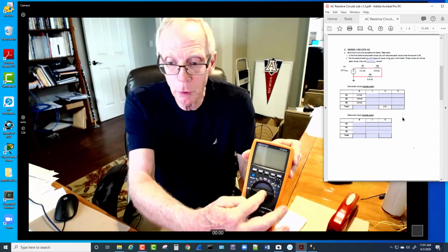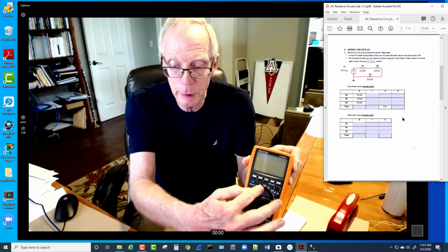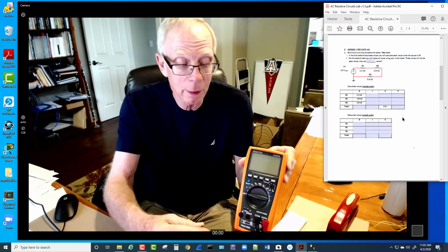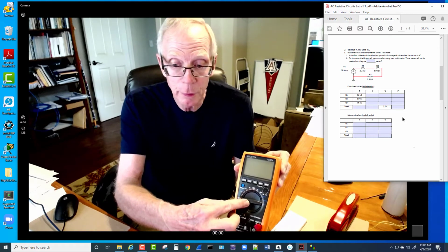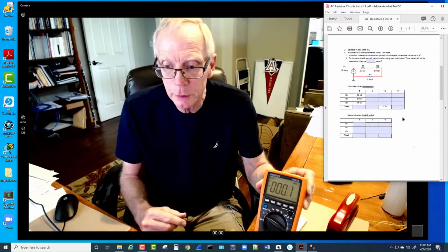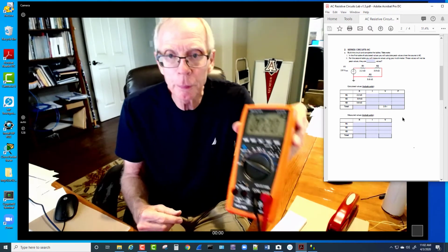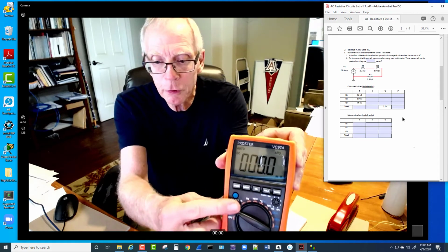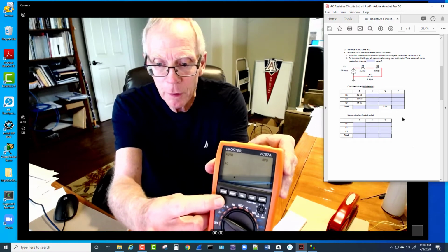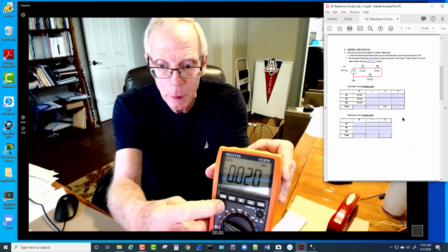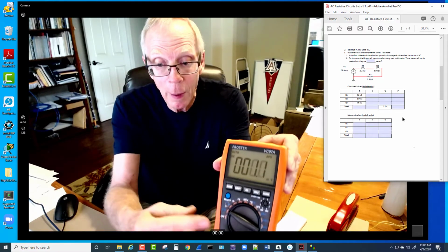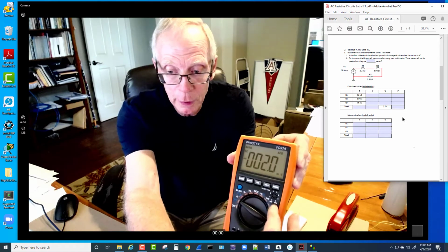There's the usual control that rotates the dial, shows you all the possibilities. In this one, for AC and DC, you don't have to keep finding a different location for it. You just flip the dial, like I'm going to flip it here to volts. I'll find it up on the camera. And if I push this little blue button, you see where in the upper left it says auto DC. If I flip it, it will go to AC. Flip back, it goes to DC. So that's how you change between AC and DC on voltages, and again over here on currents.